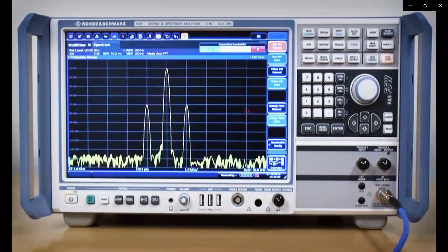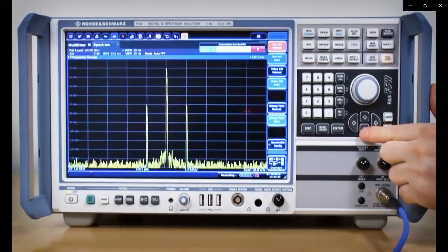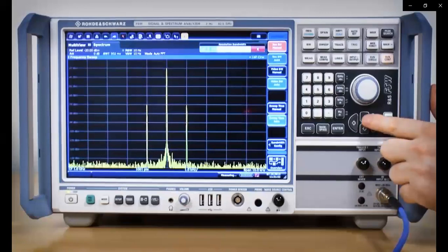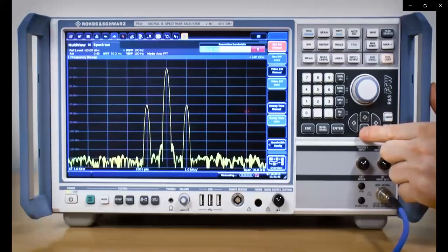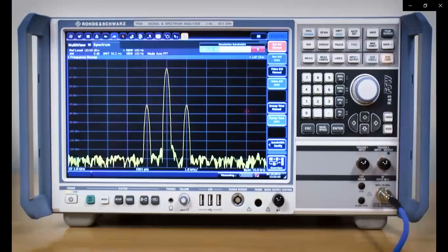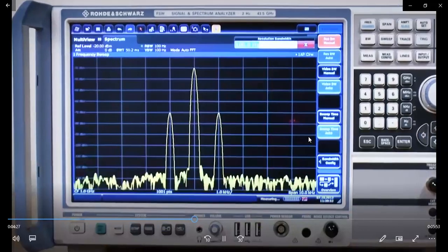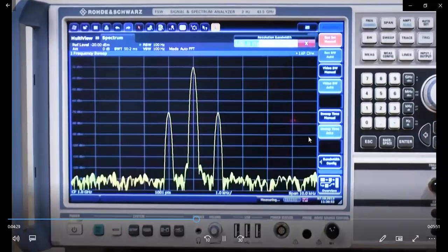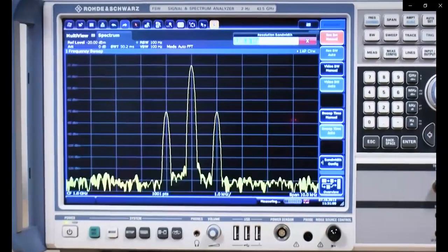This is the same as the reception bandwidth of a radio. The smaller the resolution bandwidth is, then the higher the resolution of the scan, the more detail there is. The downside to a narrow resolution bandwidth is that the scan takes longer to perform. As a result, a spectrum analyzer links narrower resolution bandwidths to the smaller overall scan widths, otherwise they just take too long. The noise level also falls for lower resolution bandwidths because the noise is proportional to the bandwidth.